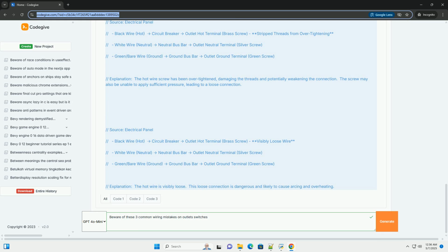Code references, NEC examples. NEC 200.11 requires the neutral conductor, identified by white or gray, to be connected only to the terminal or conductor intended for it.